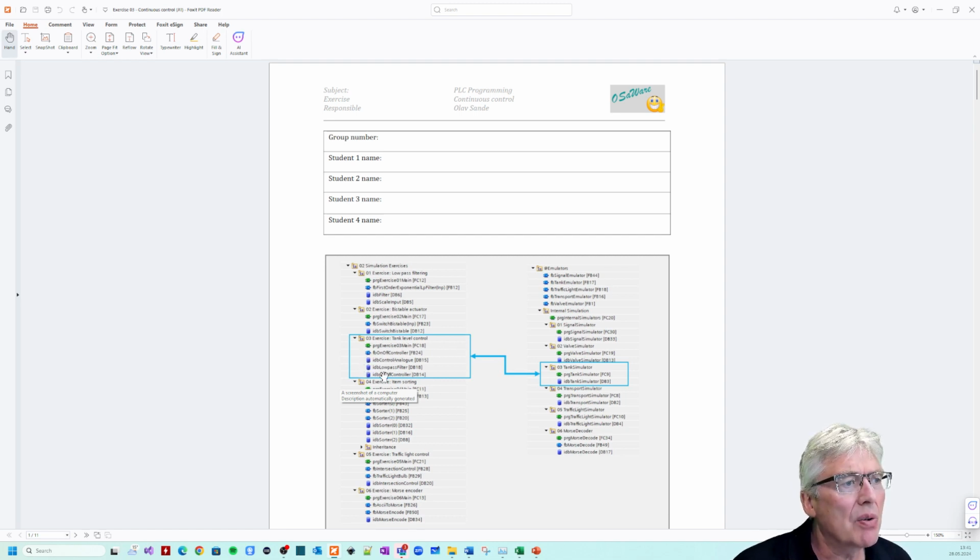Then there is an on-off control instance, and an instance of this control analog absolute algorithm that is already in the project. And you should also use a low pass filter that was programmed in another assignment, a first order exponential low pass filter, but there is also one in the template project if you don't have this filter. So there's a low pass filter or anti-aliasing filter, because the controller that we have here does not contain an anti-aliasing filter.